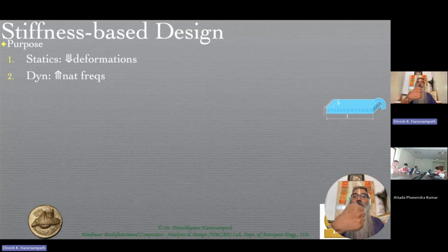Now coming to the cyclic pitch stick, when you're trying to move it forward or backward, it's a little more non-intuitive because there is a 90-degree phase lag between the pitch and the flap. So pitch, remember, is the change in angle of attack that is happening over here, to put it in very simple words, though there is a slight difference between them. Whereas the flap is the entire rotor blade going up or down, right? So now these two are coupled with each other aerodynamically by a 90-degree phase lag.